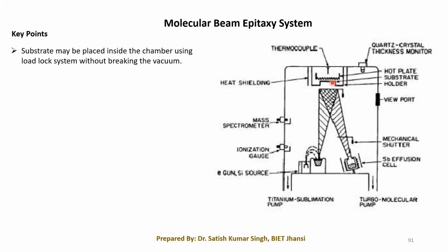We have to keep in mind that while placing this substrate within the chamber, its ultra high vacuum condition should not be broken. If it is broken, then again it will take time to evacuate it. So while placing a substrate within this system, the MBE chamber, one system which is called the load lock system is actually used.